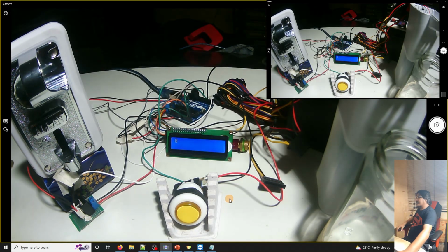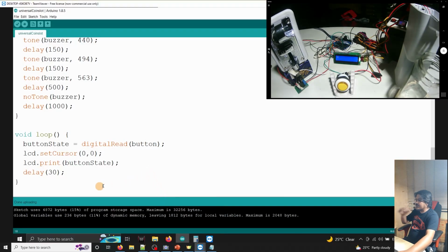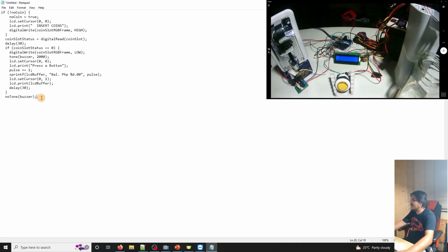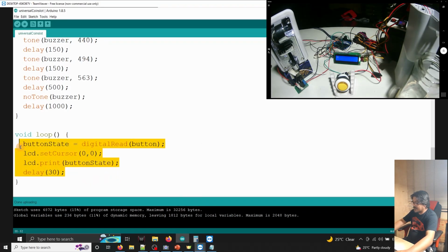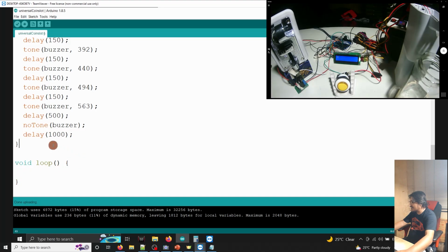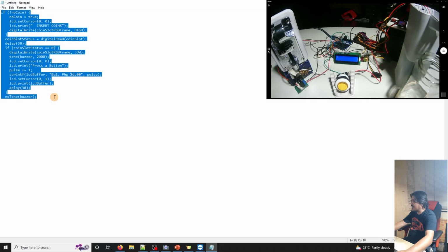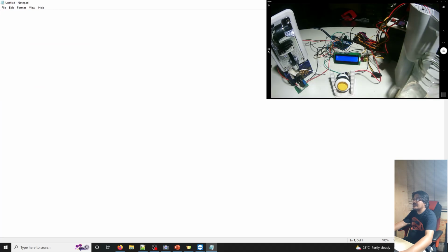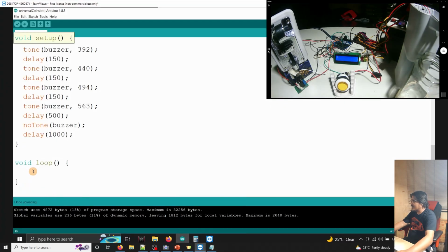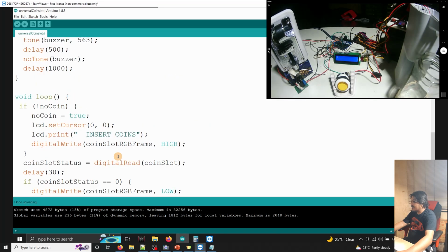That we know now what value we are looking for, if the button is pressed, it is 1, then we can continue with our original program. So, let's remove everything here in the loop and just leave the loop format like this. Void loop, okay? And if you remember, we pasted what we did earlier in Notepad. So, let's copy it again, go back to Arduino and paste it again in the loop. And then press Ctrl T to align them.